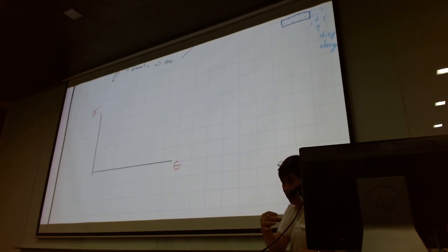So in this case, what we do is we pull the specimen until it breaks. When we start pulling onto them, it will develop the character, and you can actually do the mapping of the displacement versus the force. And you can actually convert that displacement into strains.